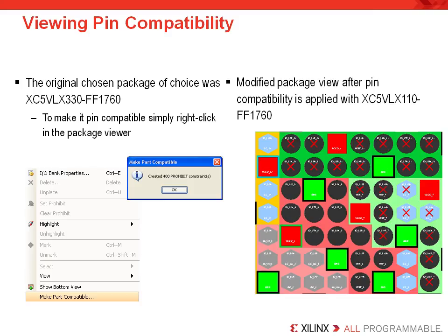The I/O Planner also has a Pin Compatibility utility that allows you to facilitate the migration of a design between two density components that are supported within the same package. This is done when designers are testing their design on a prototyping board that supports a large density and then migrates to a smaller device for shipping.